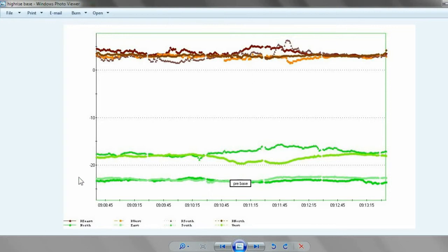If we ran our tube out at the bottom and went all the way up to the top of the building with a long length of hose, say 100 feet, and put our gauge up there, we're still going to be reading -23 down here, even though our gauge is up at the top of the building, because the weight of the air in the hose is equal to the weight of the air outside the hose, and our pressure doesn't change. Measuring pressure is dependent on where the probe exits the building.